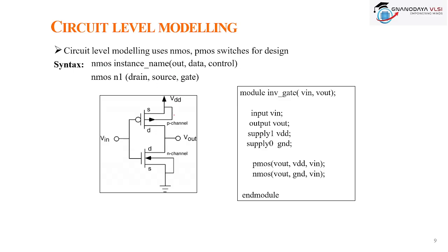It consists of NMOS and PMOS. The syntax is NMOS, instance name, then output, data, and control. The instance name is N1. For NMOS, the output is the drain, the data is the source, and the control is the gate.